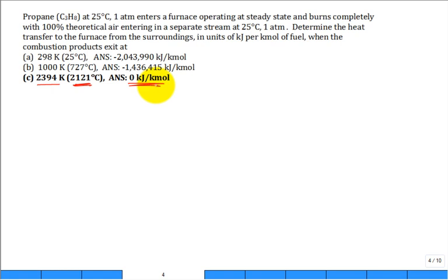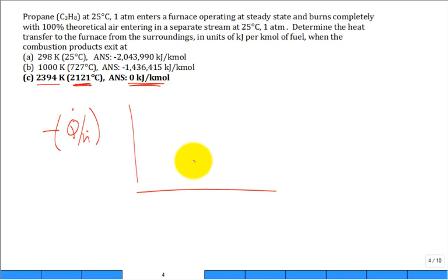What I typically do is I try and encourage students to bracket it and then do a linear interpolation for refinement on the adiabatic flame temperature. So try and do this Q dot over N dot, get rid of the negative sign. It's huge if the temperature of the products is low, maybe 298, maybe 1,000. This is a good one right here.